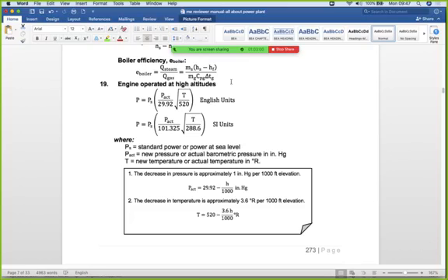But the makeup water is always fed in a preheated condition, no? Just like when we use, what was that device? Economizer, no? The economizer utilizes the heat of the flue gas, thereby preheating the makeup water, so that the difference of enthalpy is so high that when multiplied by the rate of steam, the Q, or the heat supplied inside the boiler, is also high.